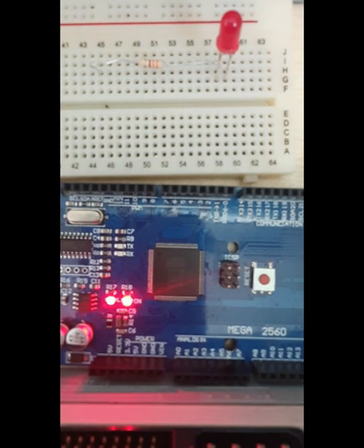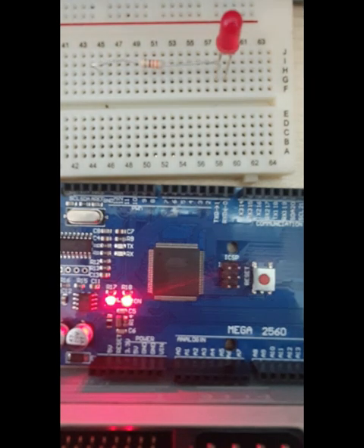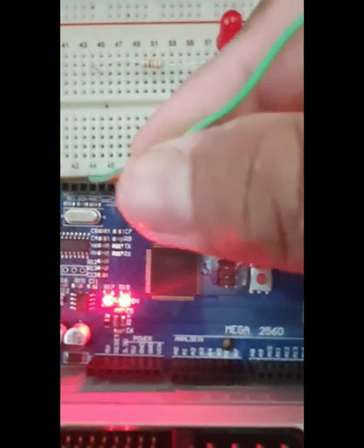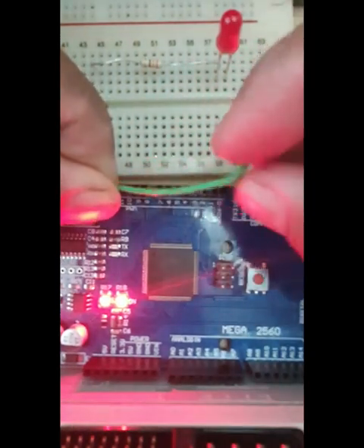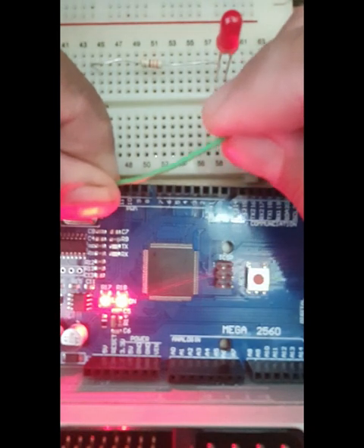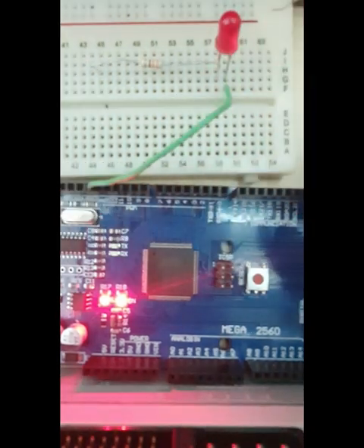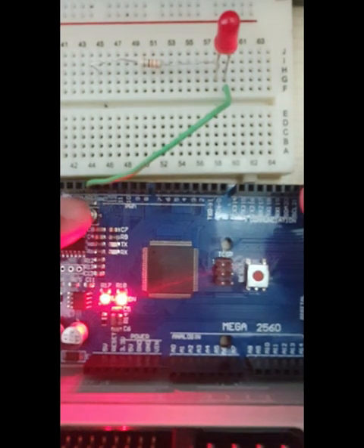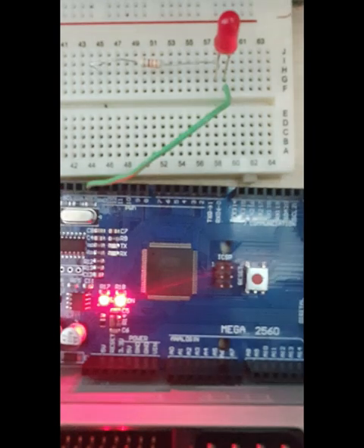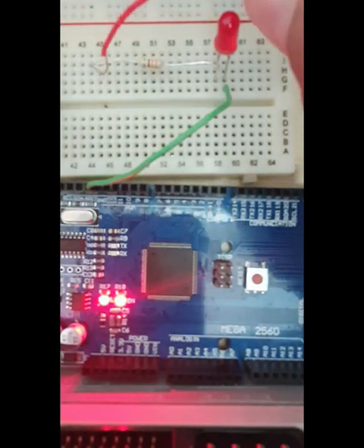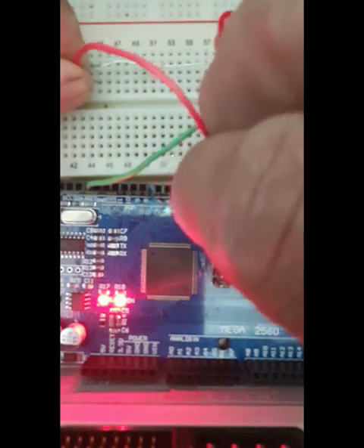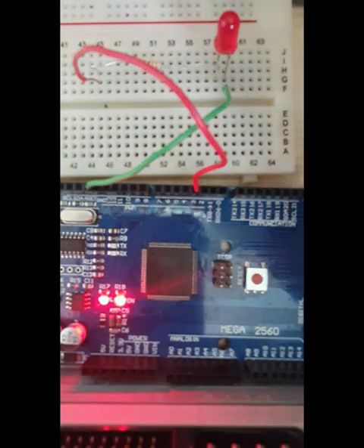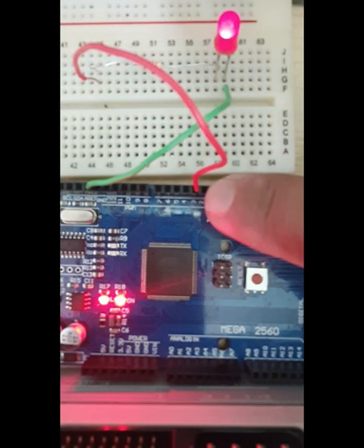The next thing is we need to make a connection between the LED negative leg and the ground connector on the Arduino board. So you see that I'm connecting the ground connector of the Arduino board to the negative leg of the LED. Alright, so you should see the ground label on that. And then the next step is that we need to put the input signal. So we put one end to the resistor, and another one at input number 3. When we have uploaded the program into the system, the LED will start to blink.